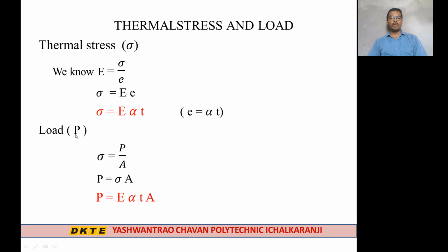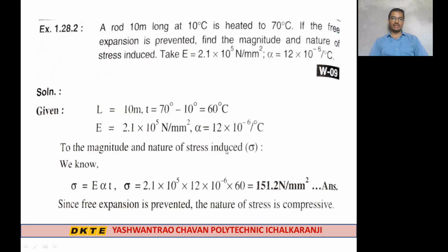And load P: we know that stress is equal to force upon area, therefore force is equal to stress into area, and the value of stress is equal to E alpha T. Put the value of sigma is equal to E alpha T into A, that is the total load. These two equations, these two formulas we have to use to solve the problems on thermal stresses. Let us discuss the first problem.